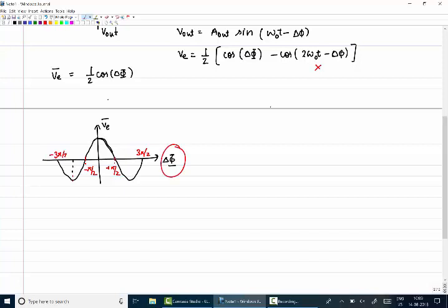If I want to have a negative feedback, which section of this phase error, on the x-axis delta phi, which range of this phase error detector is useful to ensure that the PLL is always in negative feedback? It is not going to be in the positive feedback inside the PLL loop, depending on if the phase error shifts slightly.